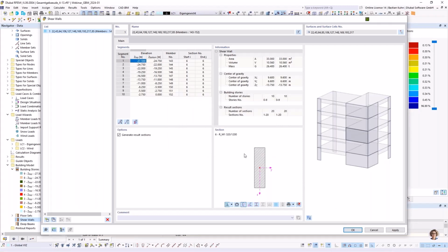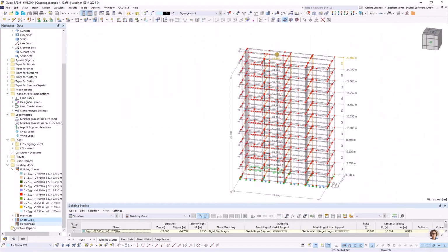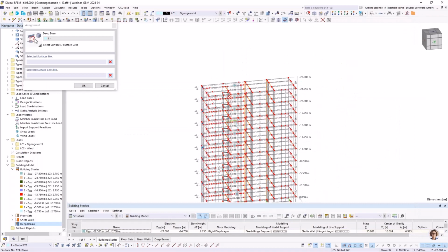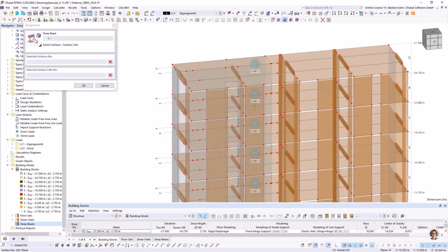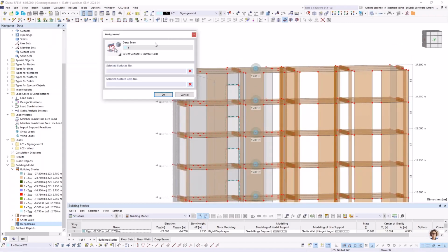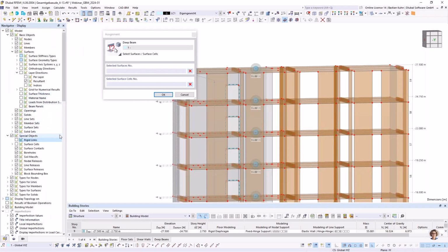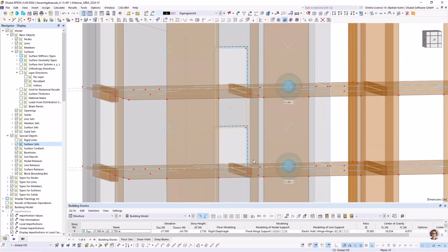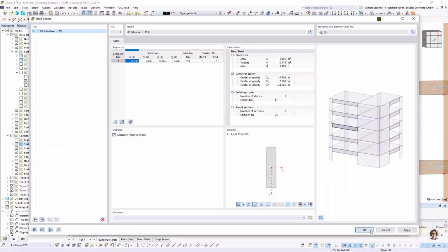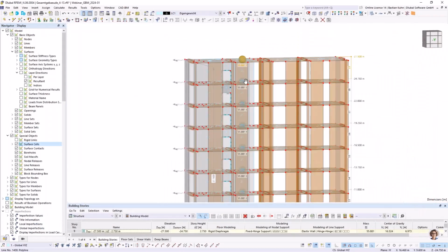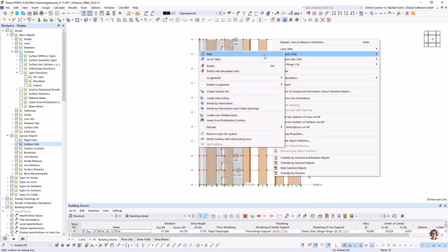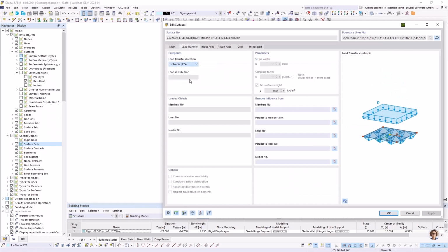All right, definitely good to delete the results here. And I also will define a deep beam where I have the opening of the building, where the staircase is. Therefore, I have to activate the surface sets, because this would be good to be used by surface sets. So we go to surface sets, and we use this here, and this can now be seen as a downstand beam. All right, say okay, and also maybe generate a result section. Say okay, and maybe also use this function in here to use load transfer X stripes right now.